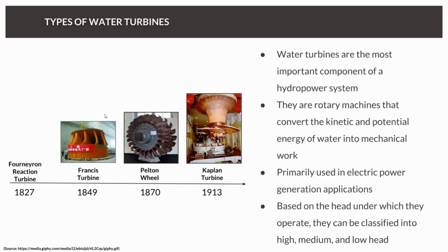There's been other turbines since. The Pelton wheel basically works at much higher pressure heads, but is not as efficient. And then the Kaplan turbine, we're going to go into these in a little bit of detail in a second. The Kaplan turbine basically uses the aerodynamic effect rather than any impact forces, so it moves very, very fast, but it can't handle a very high pressure differential. Obviously, if we needed to do that, we would have to start rotating the blades so that it didn't shear in any way, and then you would end up with a Francis turbine.